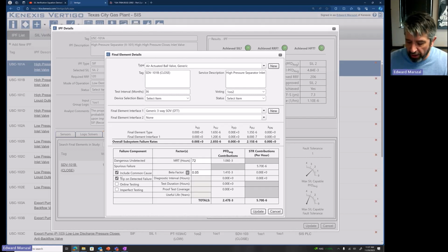You're not requiring your IPL to address both initiating events simultaneously because they can't happen simultaneously. So yes, you add the frequencies of the initiating events together, but each row in that calculation is independent from each other row, even though they might contain the same safeguards.